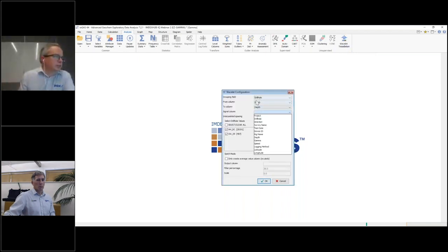Here we have a grouping field, which is just the drill hole. We've got 2 different drill holes that we want to run. With the gamma data, we have a single depth, so we set our from and to depths as the depth. If we were working with interval data, you'd put the froms and tos here. For the signal column, we just select gamma.